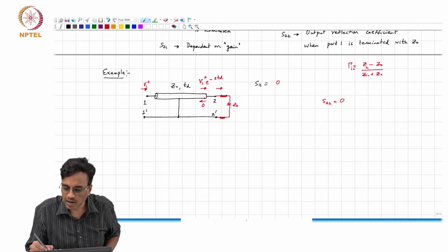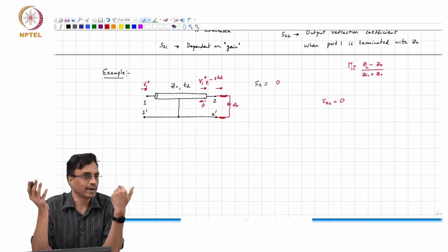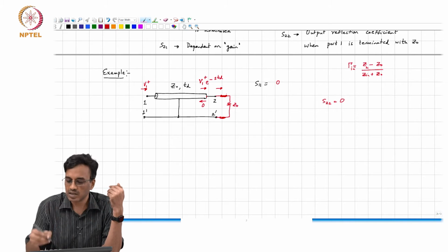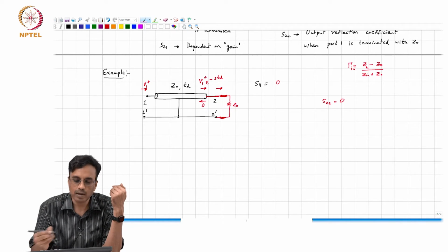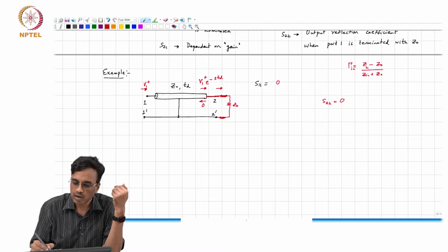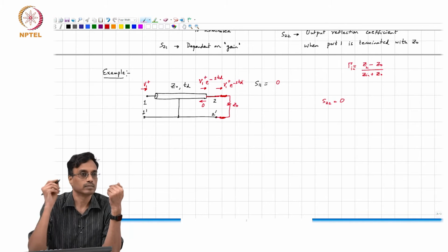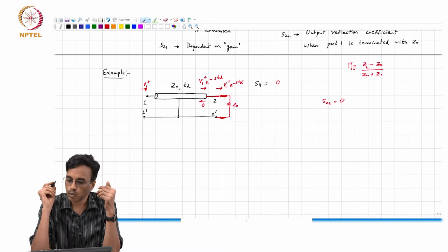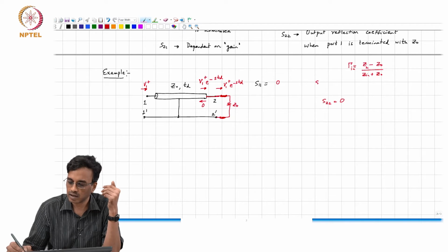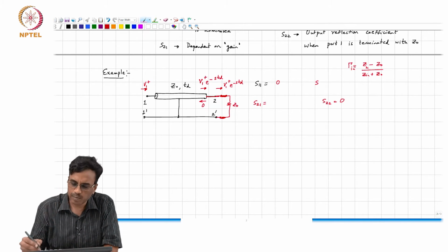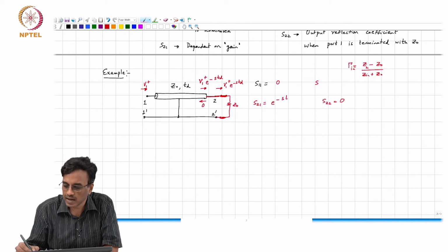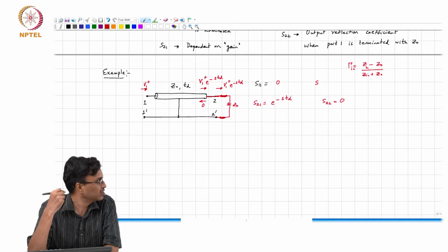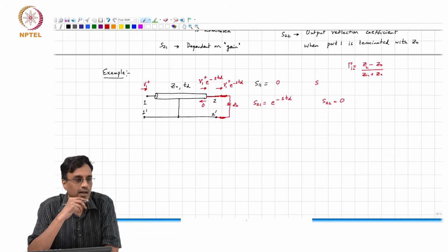And likewise, on this transmission line, we know that there is no reflected wave. So, the voltage at this point is the same as the voltage at this point, and that must be simply equal to the amplitude of whatever the forward going wave there, correct. So, what comment can we make about S21? It is simply e to the minus s Td, or on the j omega axis it is e to the minus j omega Td.